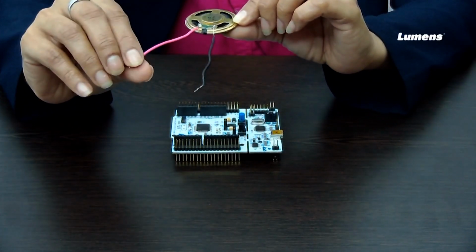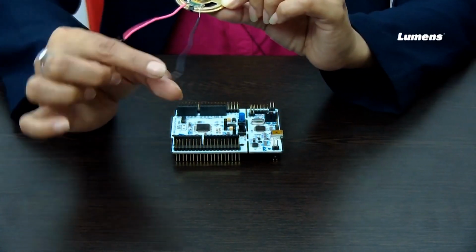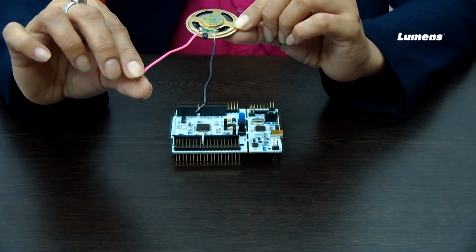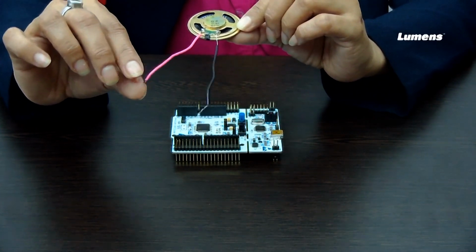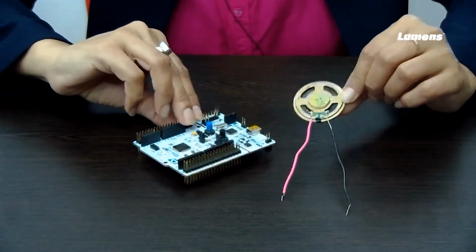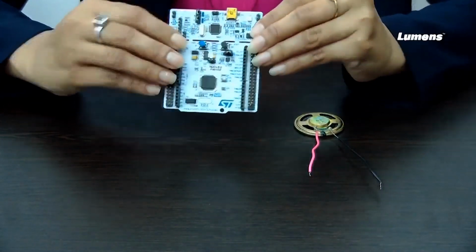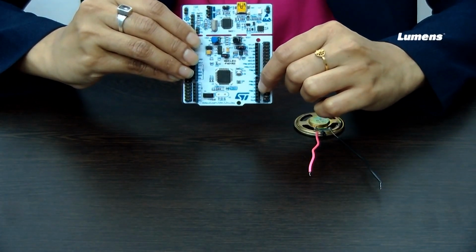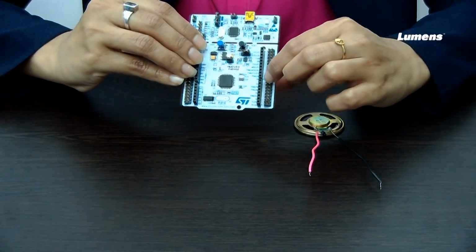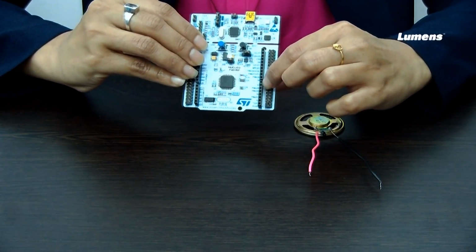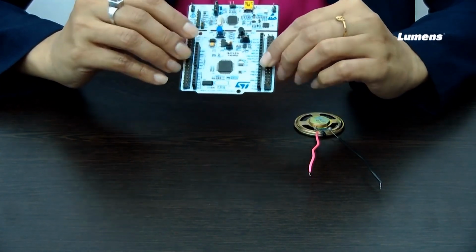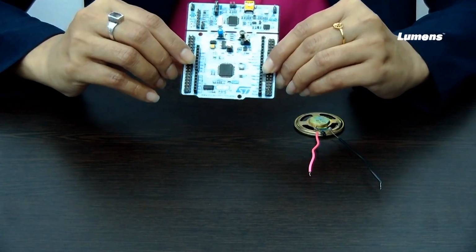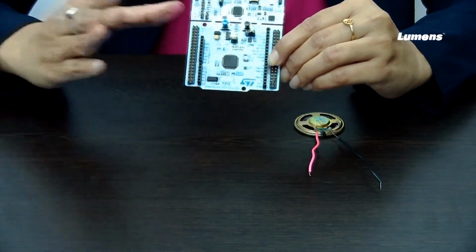What I will do, you can connect any of these ends. One end I will put into the ground, and the other end I will be putting into the PWM port. In this board there are many PWM ports, out of which I will be using the D3 port. So, I will be connecting one end to this D3 port, which is an output port as well as PWM, and another one I will be connecting to ground. This is the connection that I will make, and then I will be dumping the 4 codes, as I said.